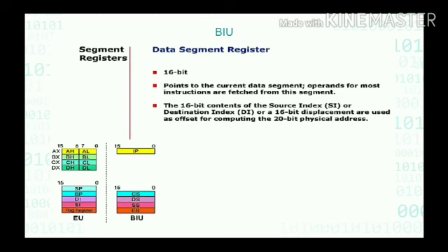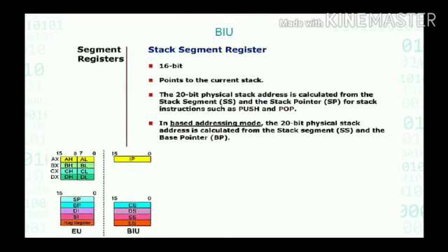Next one is stack segment register. Same, it is also a 16-bit register. It points to the current stack. The 20-bit physical stack address is calculated from the stack segment and the stack pointer for stack instructions such as push and pop. In based addressing mode, the 20-bit physical stack address is calculated from the stack segment and the base pointer. It handles memory to store data and addresses during the execution.